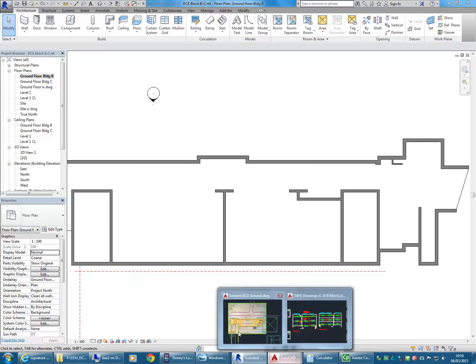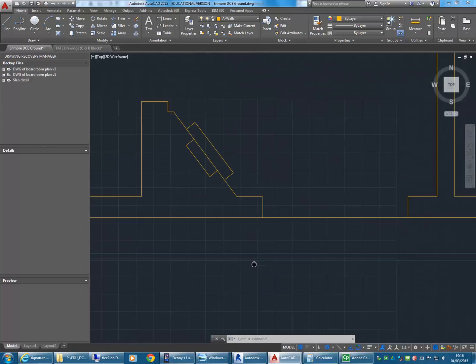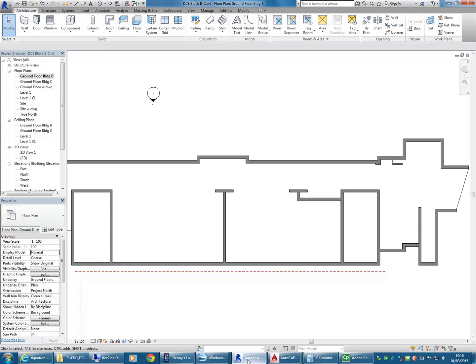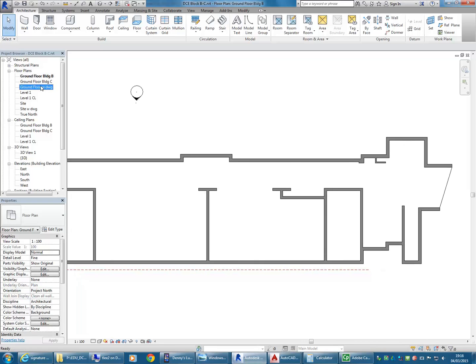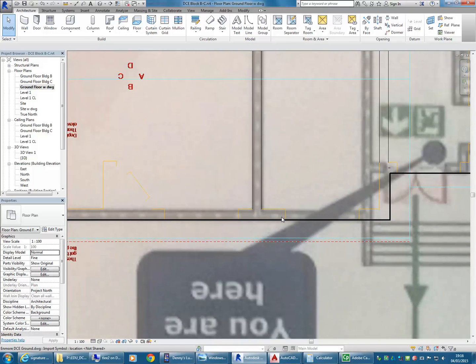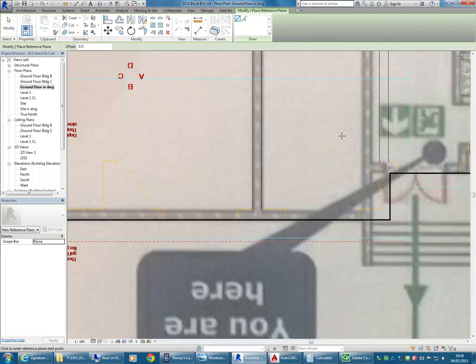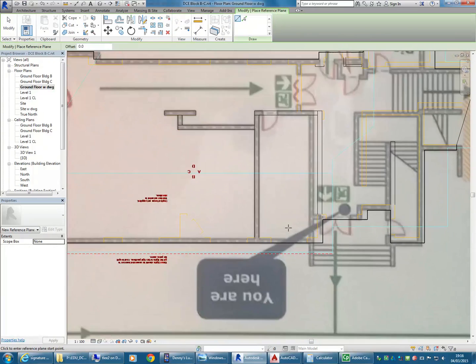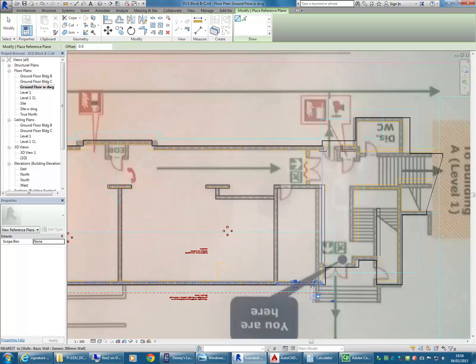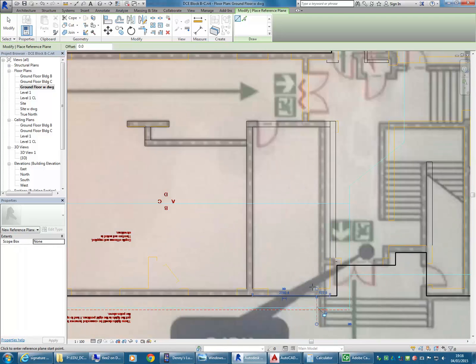And so in my AutoCAD drawing, you can see that I have started to work out the sizes. But in Revit, you don't want to draw in all of those lines to establish your openings. Just do some reference planes. And then you might see how they relate going through the building. So just with a reference plane, I'll snap here to, say, this corner. Just take it down and then stretch it so that it goes up the other way.